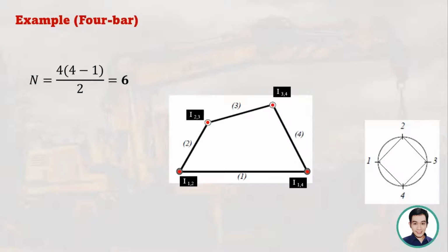As you can see, we were already able to get 4 out of 6 instant centers just by inspection alone. The remaining instantaneous centers are virtual instant centers, so we have to locate them by using the IC circle that we already established, according to Kennedy's rule. So how do we make sense of that rule?